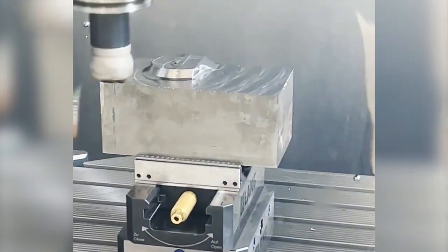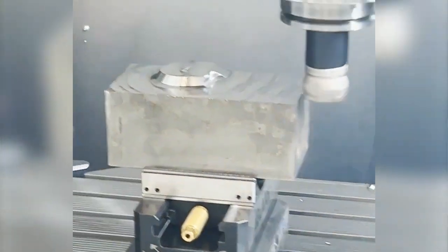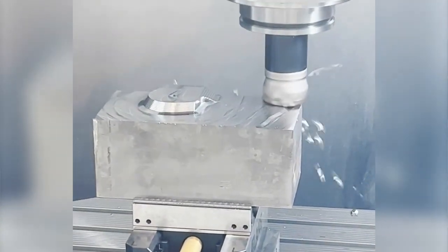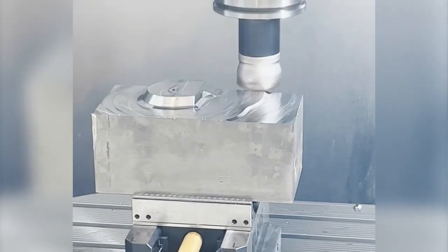Firstly, the streamlined user interface reduces the need for manual input, saving your precious programming time. Secondly, this operation includes advanced capabilities such as automatically applying cut patterns based on the part's geometry. When machining open areas, like in this machining example, NX uses the outside-in pattern with open area engages and retracts that optimize the machining process.